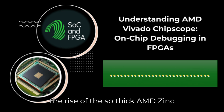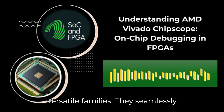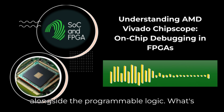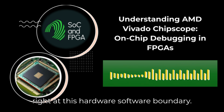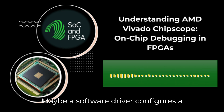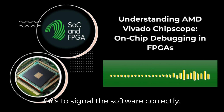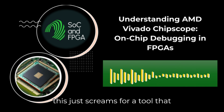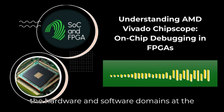And finally, you've got the rise of the SoC. Think AMD Zynq and Versal families. They seamlessly integrate multi-core processors right alongside the programmable logic. What's crucial here is that bugs often happen right at this hardware-software boundary. Maybe a software driver configures a hardware register wrong, or the hardware fails to signal the software correctly. The interface problem. Exactly. And this just screams for a tool that provides correlated visibility into both the hardware and software domains at the same time.